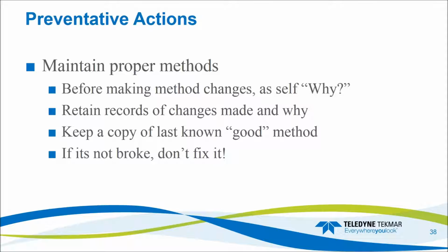Make sure you retain good records of any changes that are made and why they're made, especially paying attention to when you made the change specifically. So if you see a problem crop up, you can then tie that back to the time where the change was made and say, yes, this run occurred after the change versus this clean run that occurred before the change.